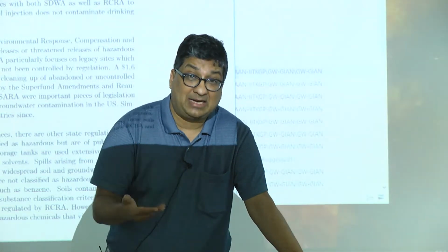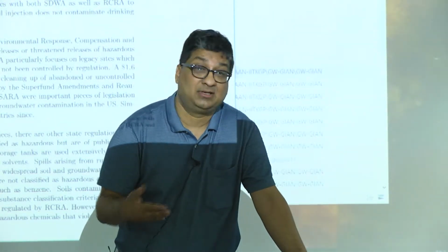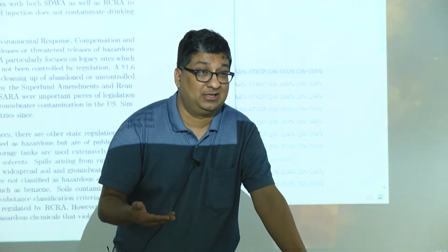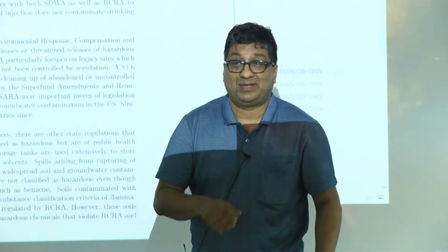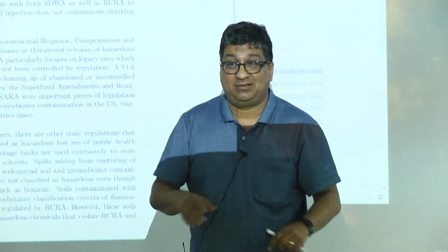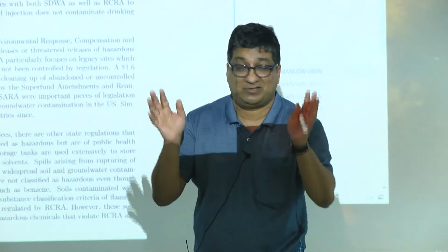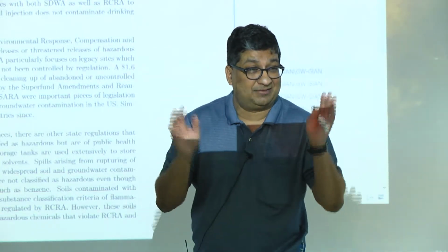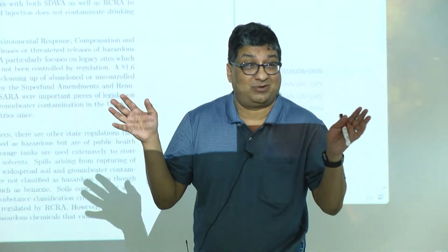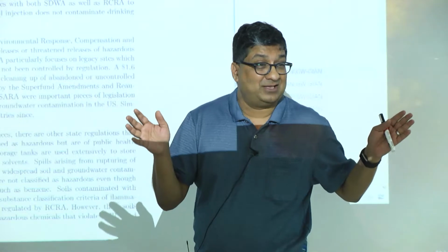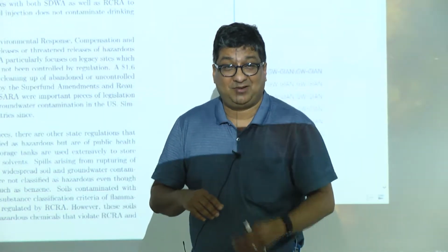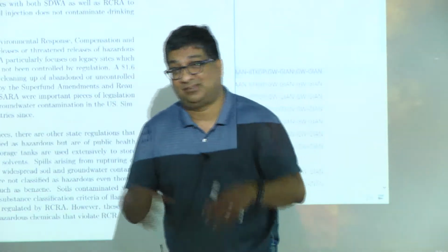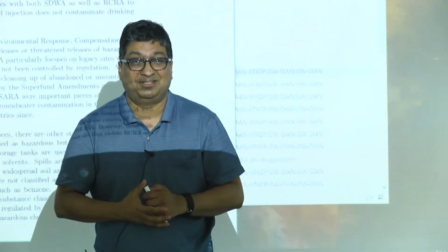Okay. So that whole process of risk assessment came out of CERCLA. Now these are fairly standard calculations. We do it all the time. We assume that people are 70 kilos, they live for so many years, they drink so much water, and they have a certain body mass, and then we come out and say, based on all this, we can say that you can have so much concentration in your water, benzene in your water, or TCE in your water, and we